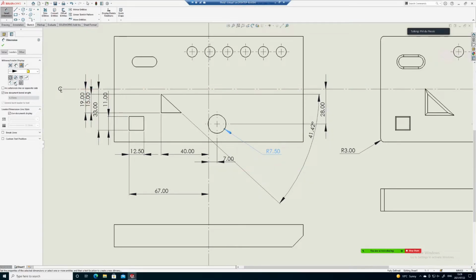So better to differentiate that that's a diameter, and then whoever's looking at it, you're trying to eliminate errors as much as possible from your side. Okay, so that's why I insist that radii get an R and complete circles get a diameter.